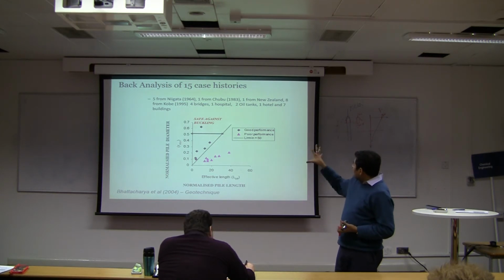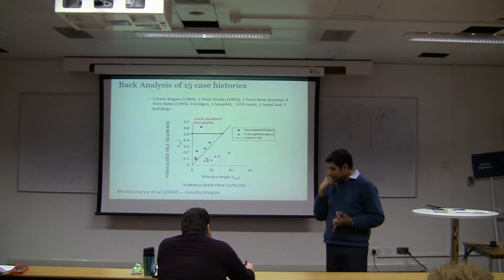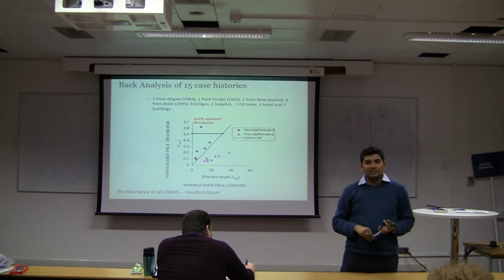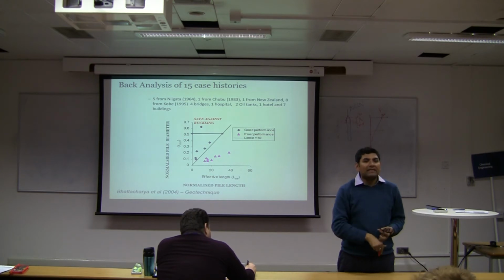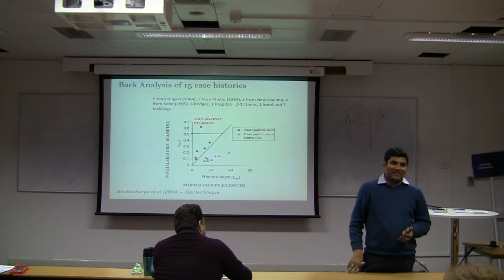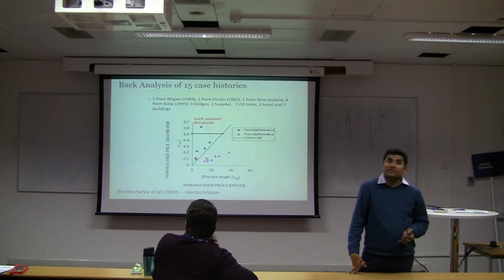And what this graph shows is that the piles that fail are all long ones. So that means, though the codes of practice say design for bending mechanism, that doesn't govern the design. The design is governed by buckling mechanism.